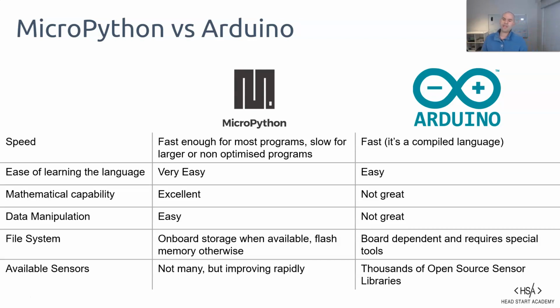And finally, in terms of advanced sensors, so you would have digital that are on-off, analog. Any microcontroller can interface with those. But I'm talking about a camera or 3-axis accelerometers. There's sensors that require specialized libraries. Now, there are libraries for every possible sensor that I've seen out there in Arduino. In terms of interfacing with a random device, Arduino is still a lot better than any Python microcontroller. So I think that covers that.